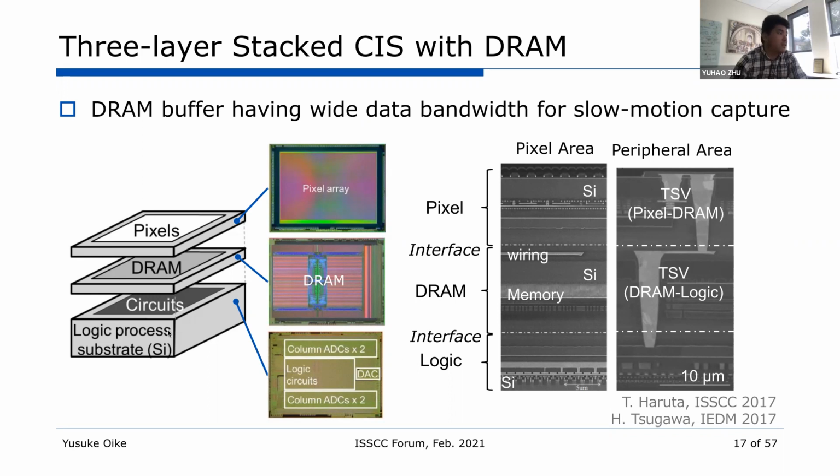This is literally CMOS logic here, and the DRAM is just conventional low-power DRAM, I suppose. And I was wondering, why must we use DRAM here? Because the amount of input data is quite huge. Well, it doesn't have to be DRAM. Meta had an ISSCC paper this year where they used basically SRAMs. It doesn't have to be DRAM.